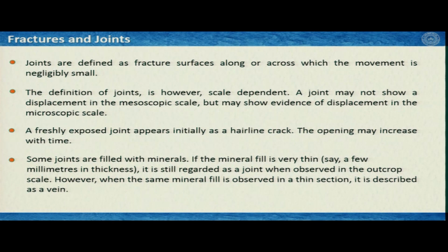Now, a freshly exposed joint, that is, a joint that has just formed and been exposed on the surface, appears as a hairline crack, a very thin line. The opening may increase with time when weathering or other natural processes act on these joint surfaces. Then we see opening along this surface, and eventually the rock breaks and falls apart along the joint planes. That happens very frequently, and this is quite normal and common. Some joints are filled with minerals.